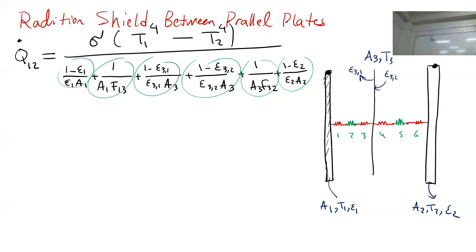the last important case in radiation of this type, which is if you have a re-radiating surface. Imagine those ovens or furnaces, if there's a good portion of heat, they re-radiate off another surface with a very shiny coating, so all the heat can come back again to this side. The other side of that shiny surface is insulated, so that's good for re-radiation. What if the problem statement says there's a radiation shield or a reflective surface in between them? Yeah, that's a good point.